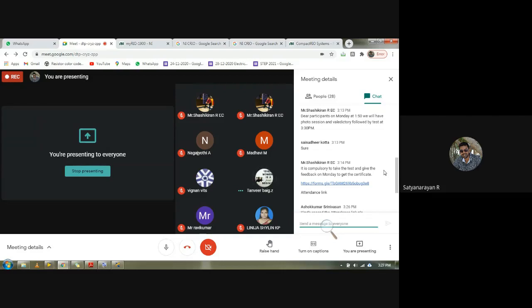One thing is we can connect our myRIO to the network, like whatever I have shown you, sir. Connect to a wireless network. Obviously, even our laptop will be connected to the same network, and we can easily read or write from an IoT file. IoT, in the sense that we can control from Firebase or AWS or UBIDots. We have different sorts of platforms. We can send and receive data through myRIO.